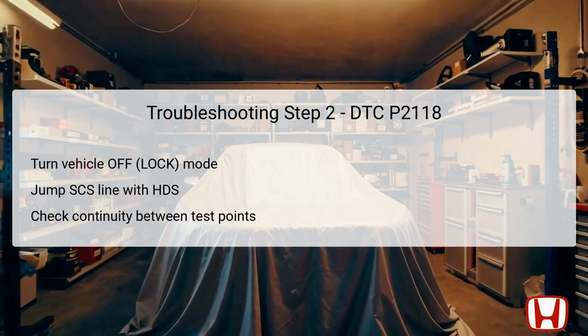After waiting for more than a minute, disconnect the required connectors, the PCM connector E80P and the throttle body 6P connector. With those connectors disconnected, you will need to check for continuity between specified test points to ensure that there are no disruptions in the wiring.